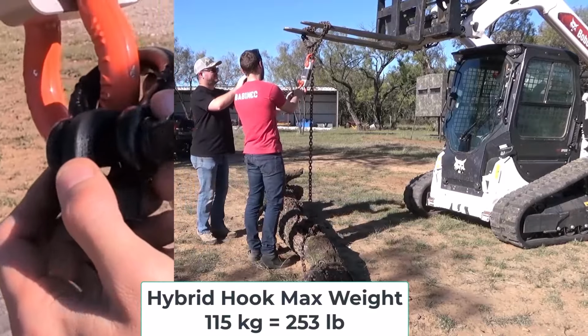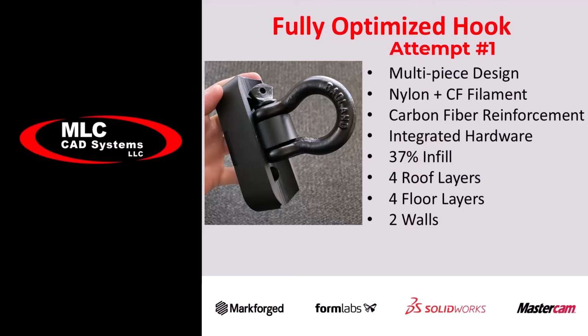Wow. Interesting. Test number 4 finally brings us to our fully optimized hook, and this is attempt number 1 to break this thing. It is a multi-piece design to take advantage of print orientations for both pieces. It's made of nylon with chopped carbon fiber filament, and then it has Markforged continuous carbon fiber reinforcement throughout the insides of this part.